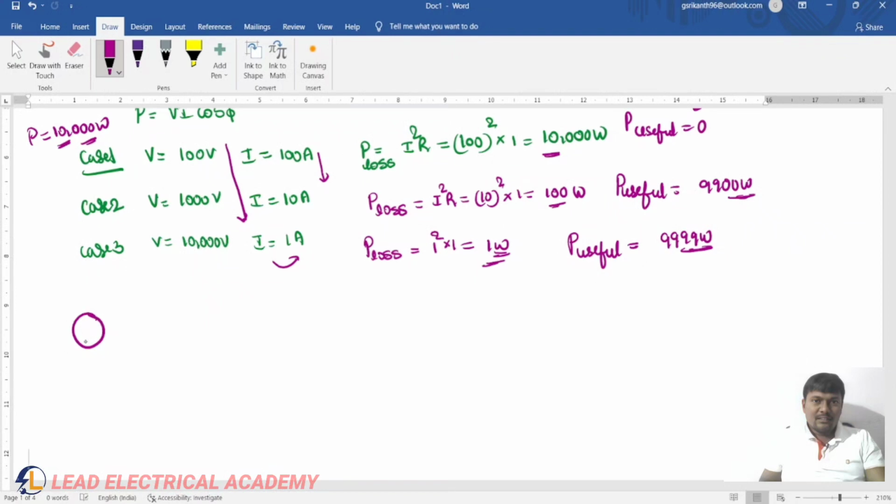So I will give the power system's equivalent diagram. At the generating station, the generator develops 11 kV. That 11 kV is stepped up to 220 kV. But in our homes we are using only 230 volts for single phase and 400 volts for three phase. So we can't utilize this 220 kV. Why are we going for higher voltages? In order to reduce the transmission losses.